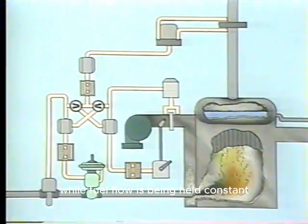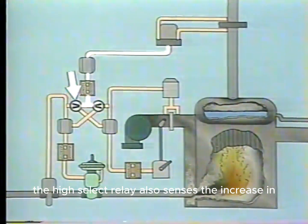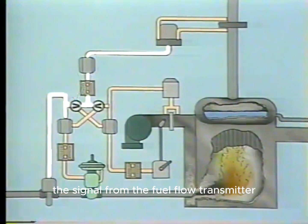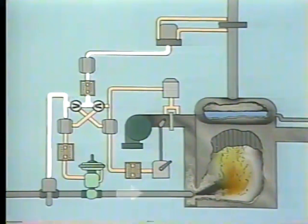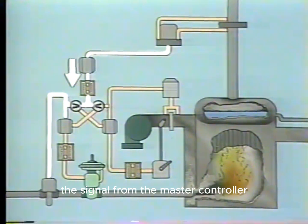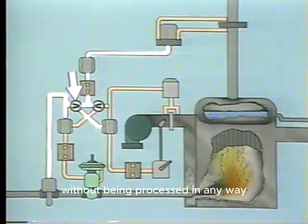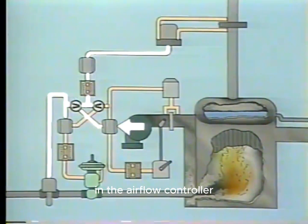While fuel flow is being held constant, the high select relay also senses the increase in output from the master controller. The high select relay compares the signal from the master controller to the signal from the fuel flow transmitter and selects the higher one to be its output. Since fuel flow has not changed but steam flow has, the signal from the master controller is the higher of the two. The relay allows the higher signal to pass through it without being processed in any way. This higher signal becomes set point in the airflow controller.